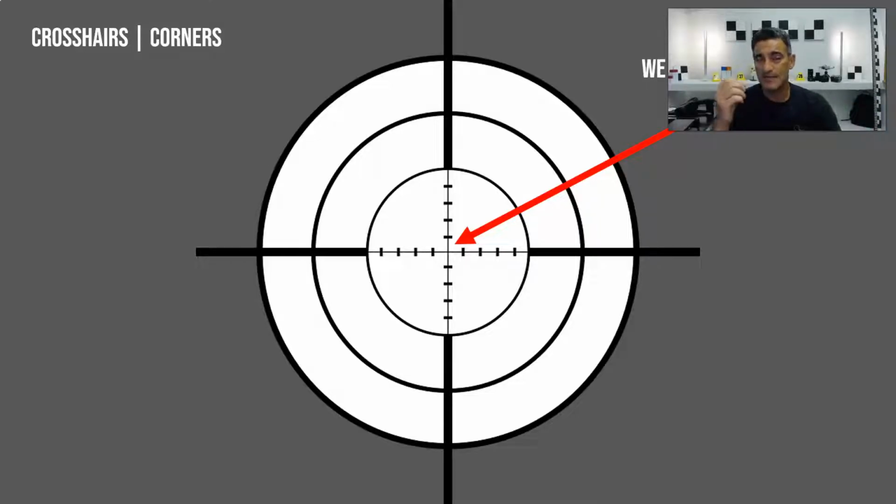being able to locate a very, very discrete point means you know where the measurement is taken from, but it also means that you can go back in the future and locate it again in the case where you have a permanent marker or whatever it is. You know, sometimes there's a plate or a physical thing, a screw or something that's not really going to move that you can go back to. So having a very specific coordinate, an XYZ coordinate, is something that you can always go back to.